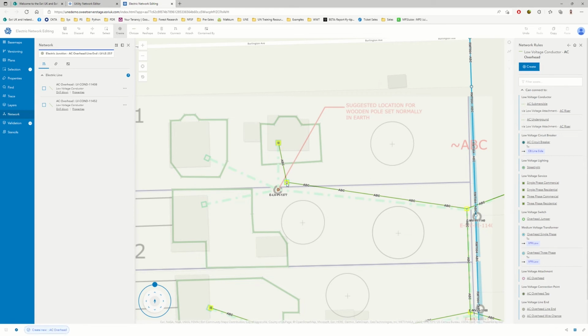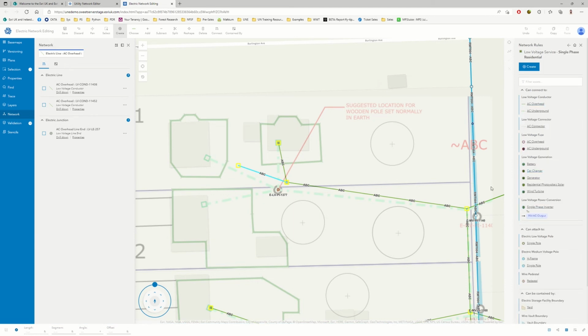In this case, I made a mistake by dragging it the other way around. And we can again see one of the powerful functionalities, in this case the reshape functionality. Let's assume we make a mistake and place these edits in a wrong position. The reshape functionality allows us to edit and make the changes requested as per the plan. After we select this line, we can hit the reshape functionality and just move the line to the requested position.